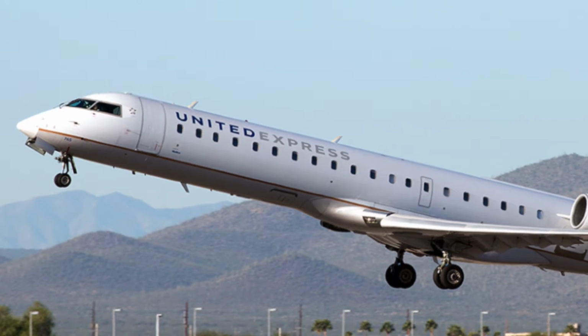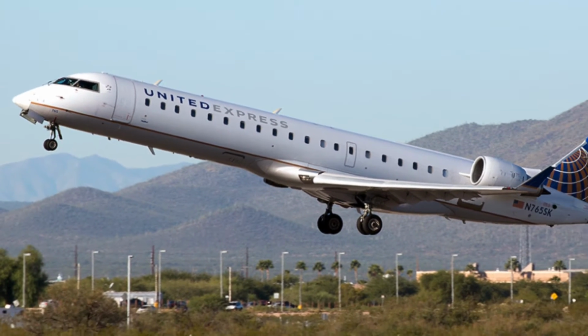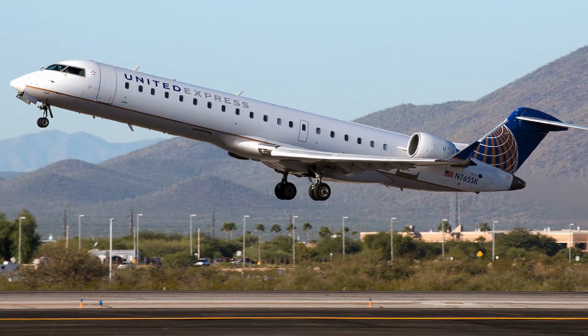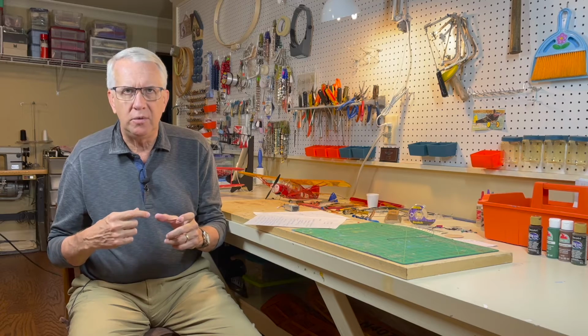I know when I was flying the CRJ-700, it was a 70-seat regional jet. We had to do a weight and balance computation for every takeoff, as every aircraft has to do. But because it just had 70 seats, we would have two zones that the engineers told us to consider, Zone 1 and Zone 2. There had to be certain minimum weights in each zone. It was not unusual that we'd have to move passengers from an aft zone to a forward zone to make sure we're at the proper center of gravity, depending on the fuel load for that flight.